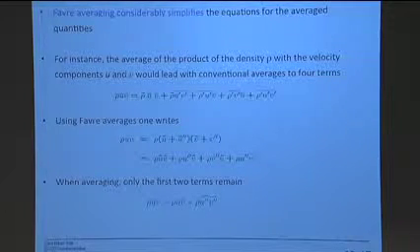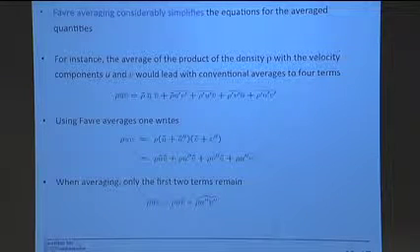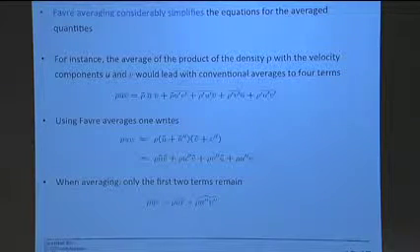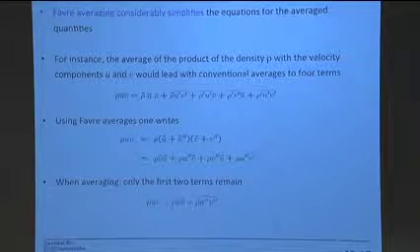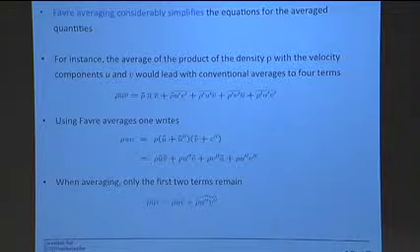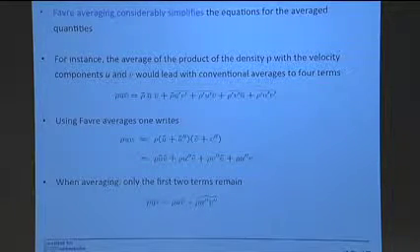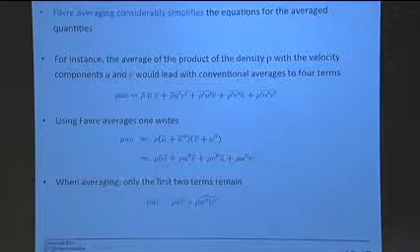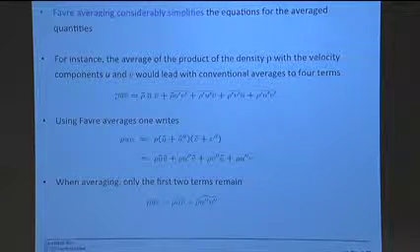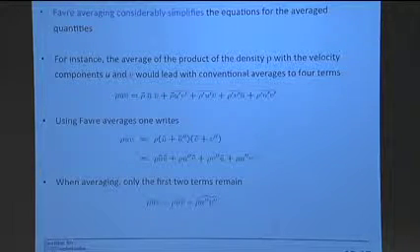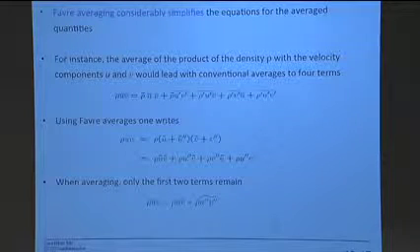Take this term. This is a term that appears in the convection term of the momentum equation, the nonlinear term. If I introduce this Reynolds decomposition in here, I get u mean plus u prime, and v mean plus v prime. I get this term with the means, and then I get rho mean plus rho prime, and all these terms that are correlations of different fluctuating quantities.